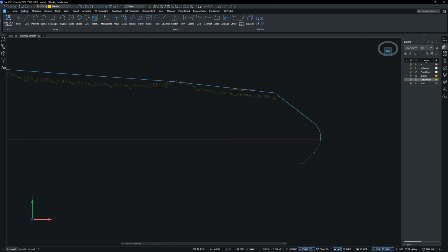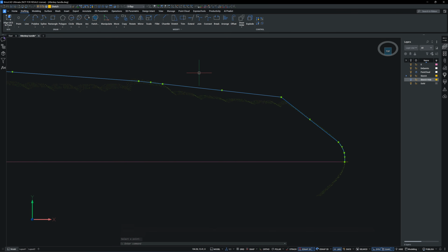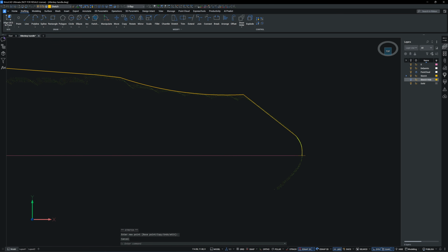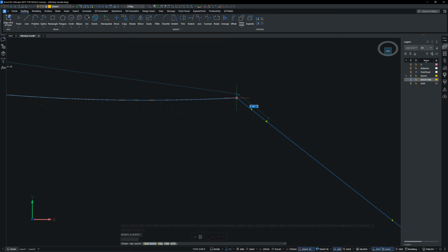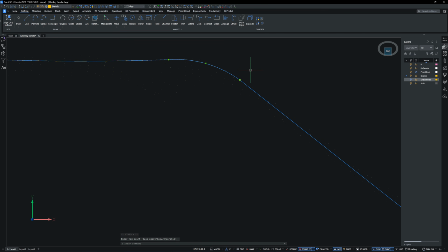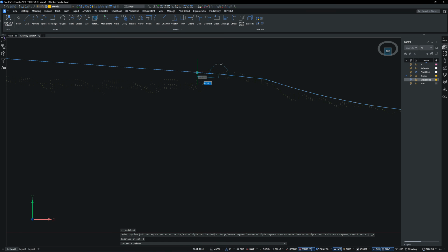I have decided to model the finger rest area together with the surface modeling, so I went back to the first sketch to adjust the curve. Since each sketch plane was placed on a specific rotation axis, it's easy to align the UCS to any sketch plane. You can also use the UCS entity command to align the UCS directly to the curve you want to edit.